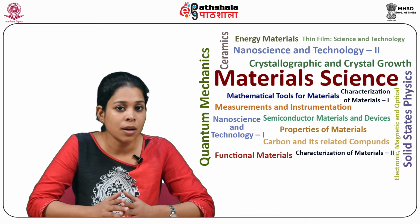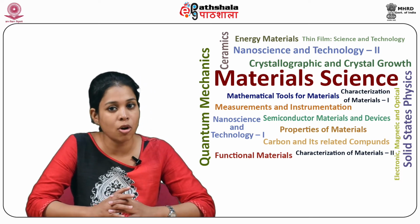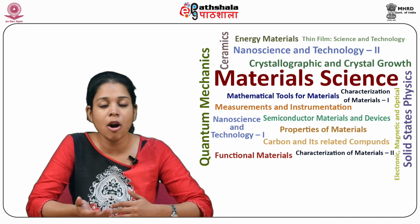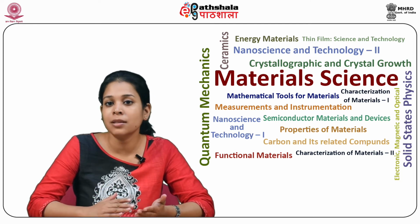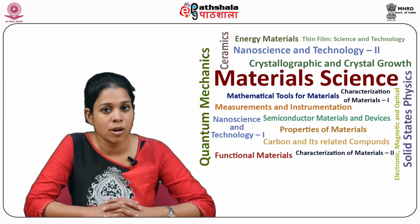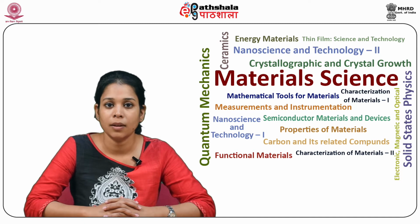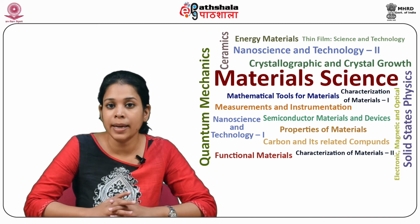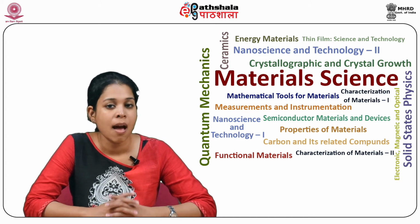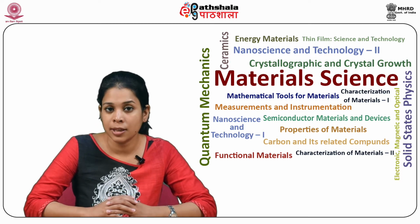Now, ionic conduction consists of a transit of ions, atoms of positive or negative charge, from one side to another through point defects, which are called vacancies in the crystal lattice. At normal ambient temperatures, very little ion hopping takes place, since the atoms are in relatively low energy states.